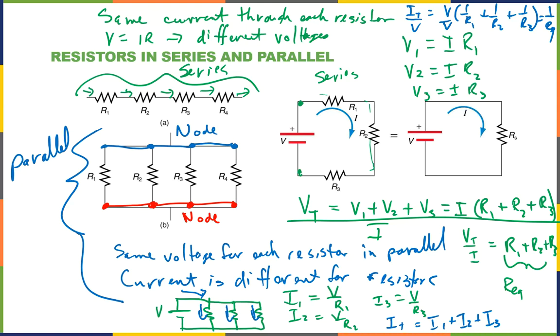Because this is what you're doing for your scientific method test, I want to make sure: do we have questions about adding resistors in series versus parallel? Okay, simple questions. If I take two resistors and I put them in series, do I get a bigger or smaller or the same resistance? Bigger. Yes, if I put them in series, it's the sum of the individual resistors.